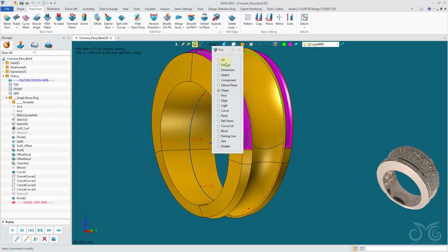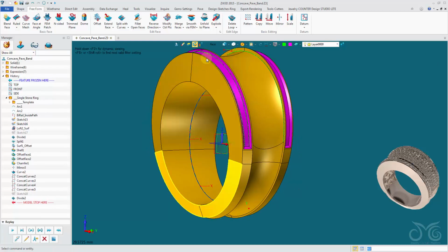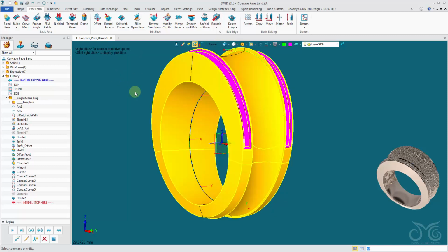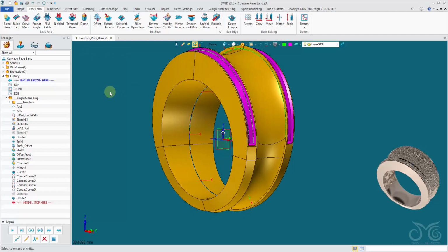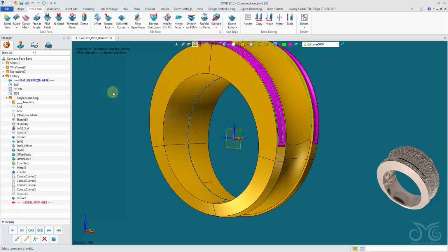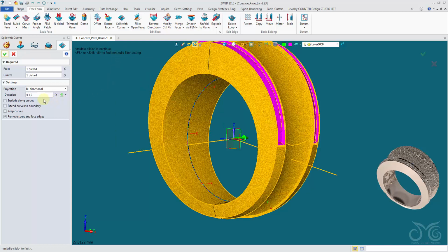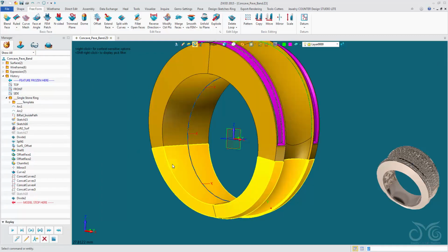And that will split the faces of my entire shape, but it will still remain one whole shape. But I want to split this up into two separate shapes. So I could redefine last and use my explode along curves option. This will explode along our splitting curves to create two separate shapes.